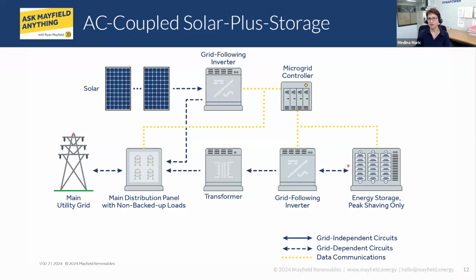If there is a solar PV inverter that is directly feeding the grid and working with the grid, it is okay. If there is storage present, then there is always a possibility of unexpected energy release and any transients and problems going back directly to the grid. So that's where the transformer and isolation play a big role. I think it also comes down to the fact that solar is just inherently current limiting, unlike energy storage. Yes, that's a great point. I hadn't really considered that one, Blair.